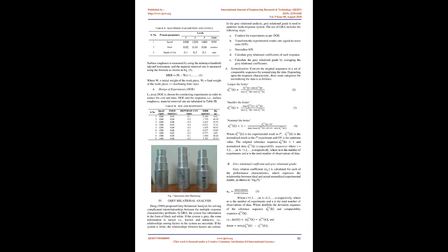Add the preheated SiC reinforcement to the melt along with a minimal amount of magnesium for better wettability, and sodium hexachloroethane was used to remove the entrapped gases in the melt. Now the melt along with reinforcement was mechanically mixed with a coated stirrer at moderate speed for homogeneous distribution, and poured into the 300 degrees Celsius preheated mold at pouring temperature, to obtain a defect-free casting.